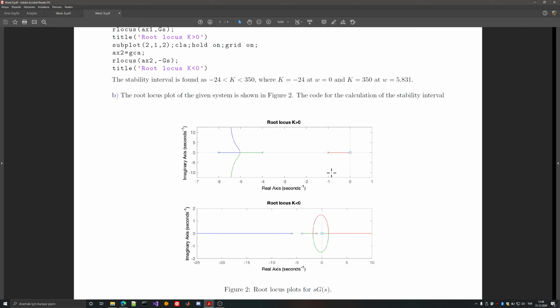the more poles you have on the left half plane, or the higher the degree of your system, the harder it will be to contain them on the left half plane, to restrict them, or to hold them on the left half plane. Because if I have fewer poles, then I need less effort to hold them, to not let them cross to the right half plane. And we will see that in a minute.